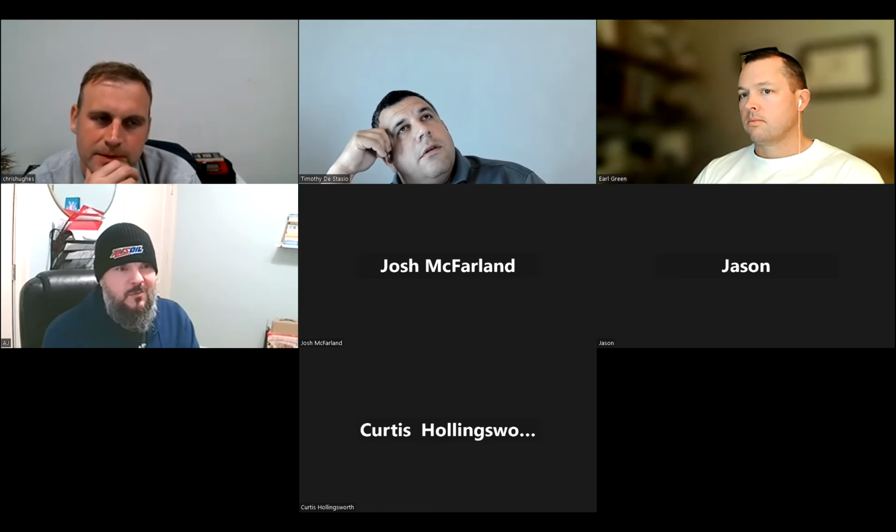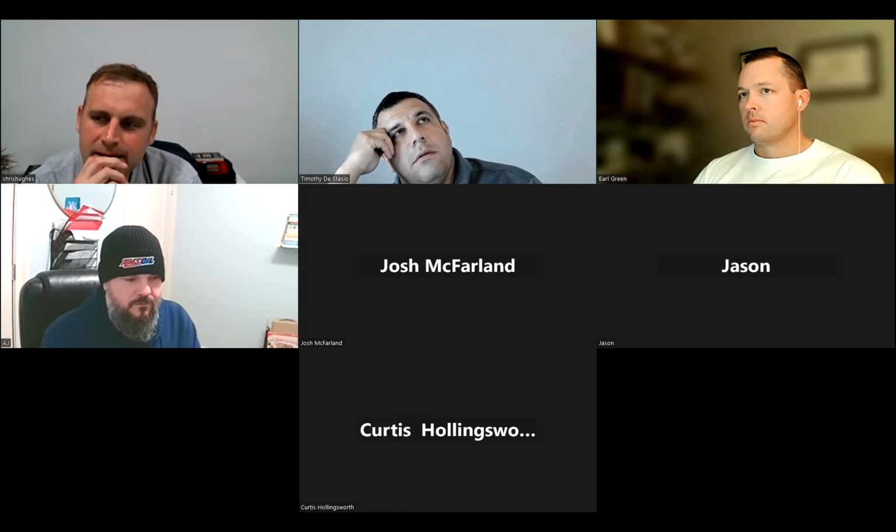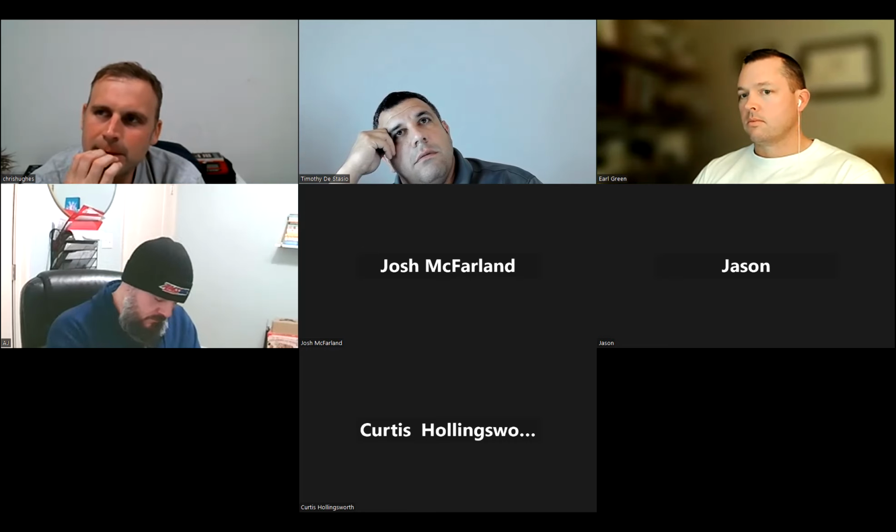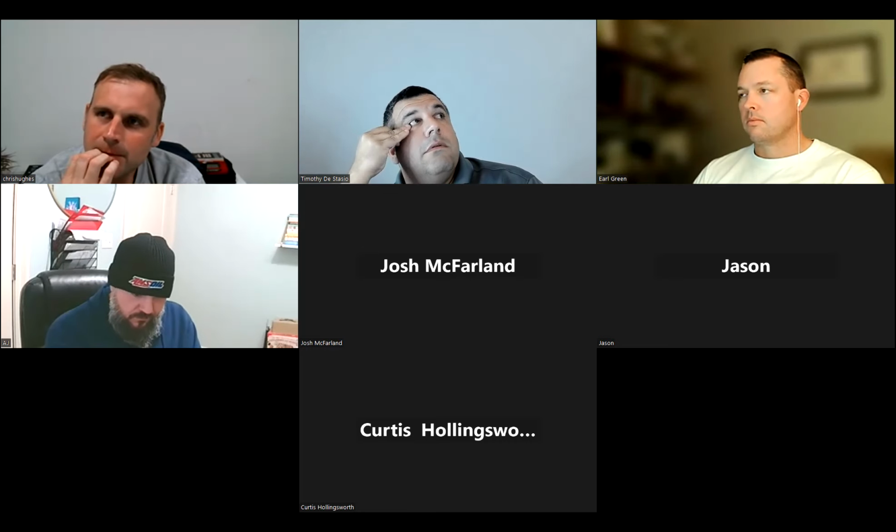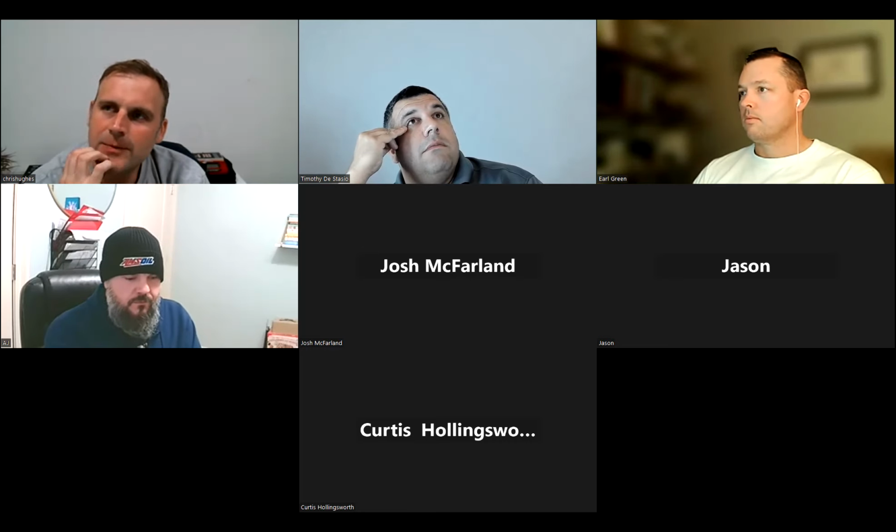Yeah, it's basically just not sealed, like no spray foam, no sealing normally. From my experience with it, I would say the house you just described to me is probably a 5 to 7 ACH50 house. Yeah, I'd say 7.